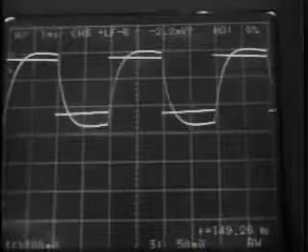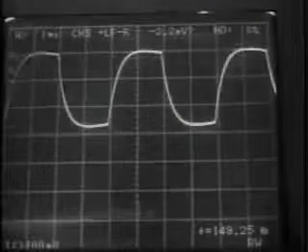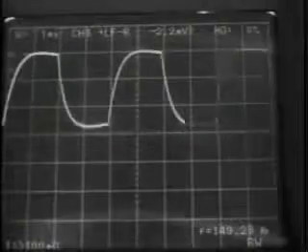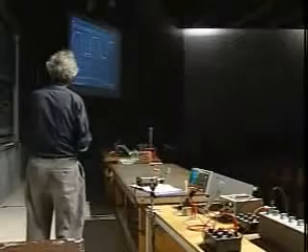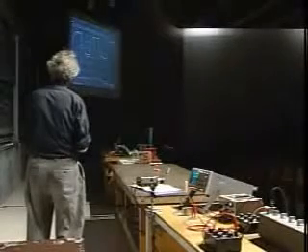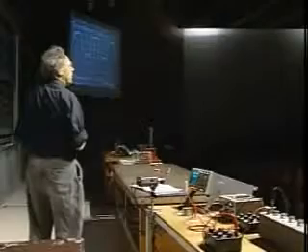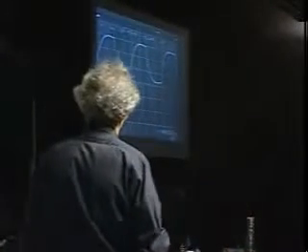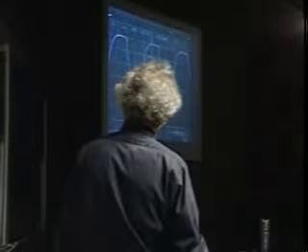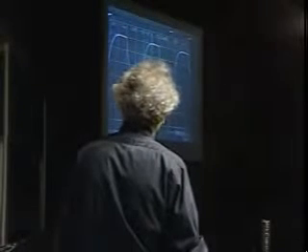And now I'm going to show you the voltage over the capacitor, and I will take the other one out. And here you see indeed exactly the image that we discussed. So you see early on the charging of the capacitor, and it reaches effectively the maximum value. You don't have to wait infinitely long. We say infinitely long, but clearly if you wait 3, 4, or 5 times RC, then you're almost there. And then here, I'm going to switch it back to position 2, and you see it's discharging.